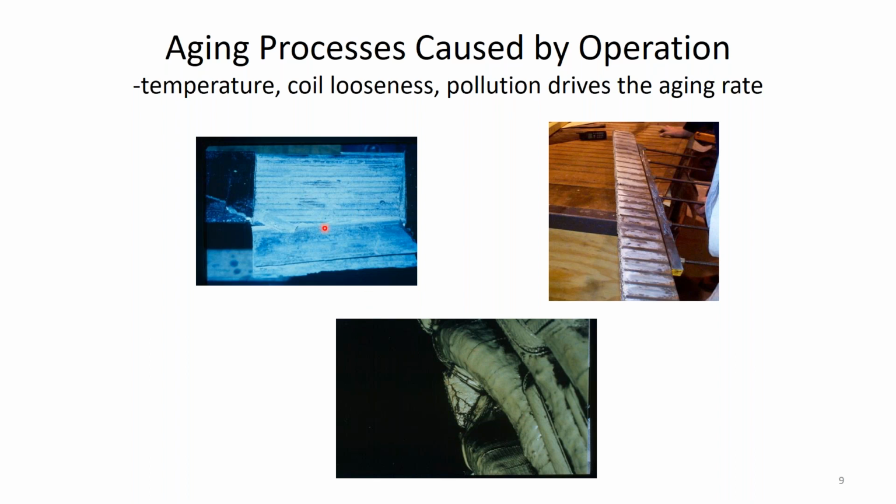So these are aging related issues. How quickly the machine fails depends on how conductive is that pollution, how high is the operating temperature, how loose are the coils. The PD itself is just purely a symptom, okay?